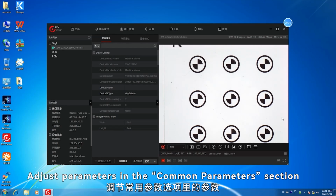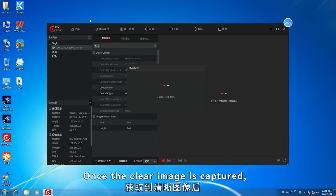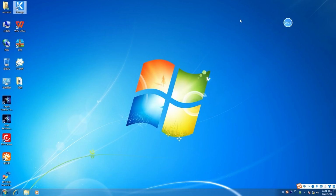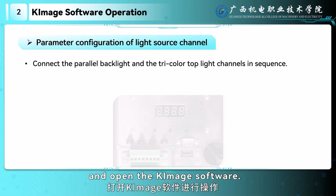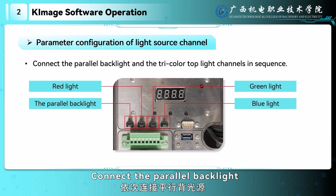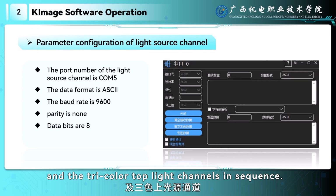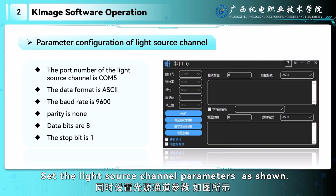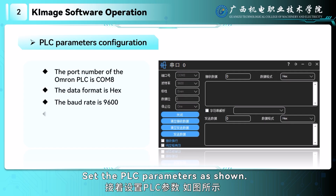Adjust parameters in the Common Parameters section to obtain a clear image. Once the clear image is captured, close the NV Viewer software and open the KiMage software. Set the light source channel parameters. Connect the parallel backlight and the tricolor top light channels in sequence. Set the light source channel parameters as shown. Set the PLC parameters as shown.